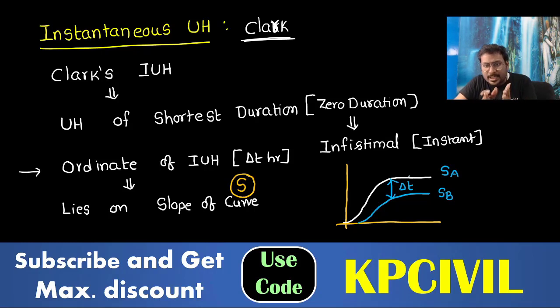So it lies on the slope of the S curve. That is called the instantaneous unit hydrograph. Two points to remember: the unit hydrograph of shortest duration is the IUH, and its ordinate resides on the slope of the S curve.